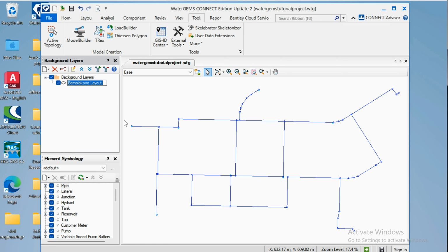So you can have those two types. You can have already the pipes and the junctions drawn in one AutoCAD file, like mine, and you do not need the contour map because you already know the junctions elevations previously and you've inserted them in Excel. Or in other scenarios, you could have separate CAD files. So you could have the contour map alone and then a node file map as a DXF file, and then you could also have a reservoir location as a DXF file and a piping network in a separate AutoCAD file. So you can have 4 separate ones: the contour, the nodes, the reservoir, and the road network, 4 CAD files, and then you need to insert all of them here separately. In my scenario, I do not need to insert the 4 of them. I can already insert just my network as one file because I already have the pipes and the junctions in one CAD file. Okay, I hope that was clear.